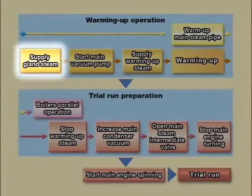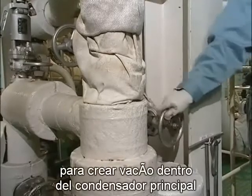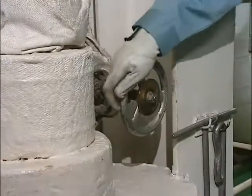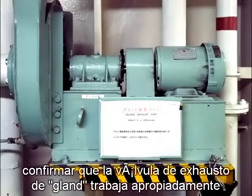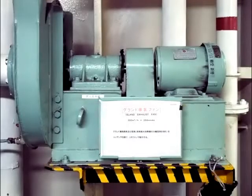Supply gland steam. To create vacuum inside the main condenser, supply gland steam to seal the rotor sections passing through the turbine casings. Confirm that the gland exhaust fan works properly, then open gland exhaust line valves.